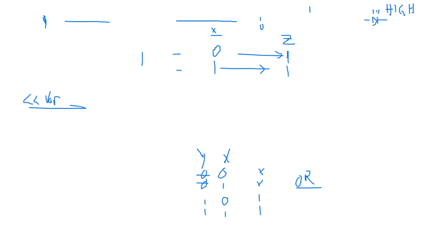So simply I can pick my signal and then use an OR with my known bit, the bit that I force to 1, and then force that particular pin to be a 1, which is the LED pin. And we know the LED pin is bit 5. So if we take our bit, and then we have bit 5, and we want to force bit 5 to a 1.